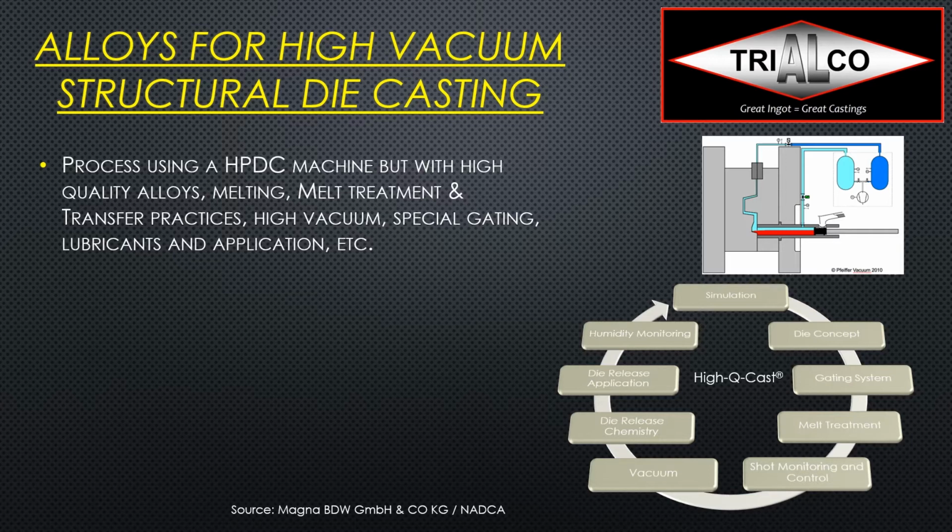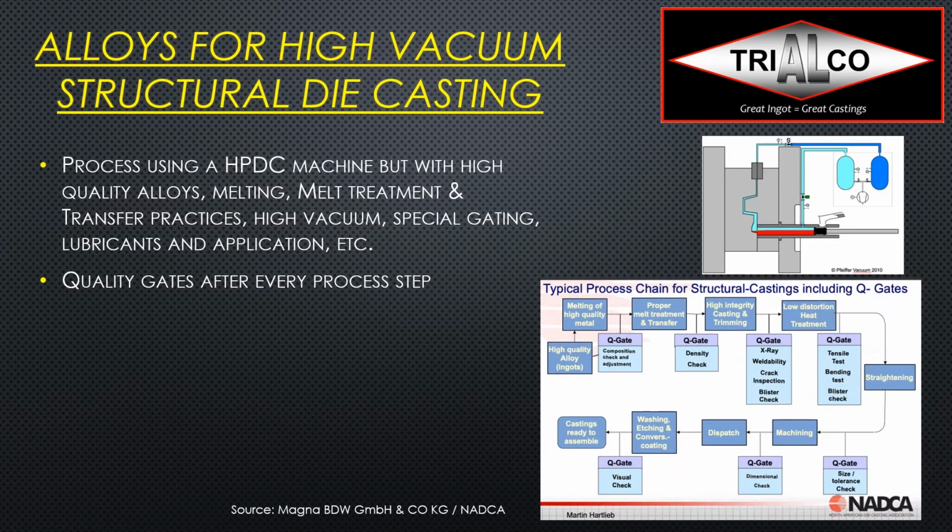I need special alloys. I need special melt treatment and transfer practices. I need special gating, special lubricants in their application, all of these things. I need a much more holistic approach to the die casting process. And then I will need quality gates after every process step. So I'm getting into much more something like you would typically see in a structural low pressure die casting facility.